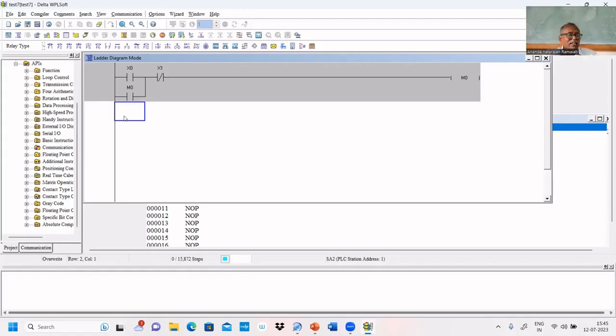If the sequence is correct, only then will that batch process work. If some other situation comes, it will not work. That's why if you stop in the middle, it may not work. So while simulating, you have to give the correct signal sequence. If you really want to write a program for real time, then you have to think of many things, but we are not doing that level.